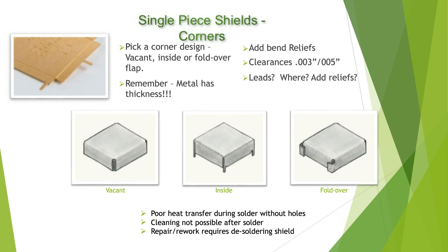If that's not an issue to you, if the product you're manufacturing is low economic value and you can afford to just throw away the bad ones, and you're not going to have to do any tuning because you don't have tunable components, you don't have to get under the shield for any reason, single-piece shields are going to work great for you.